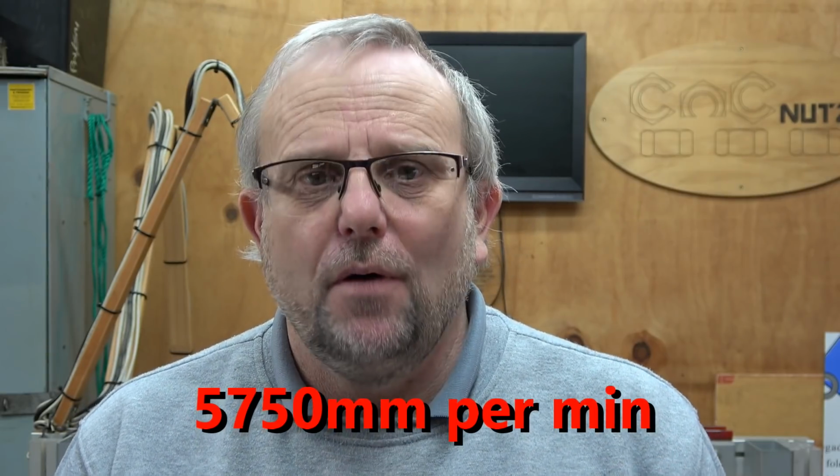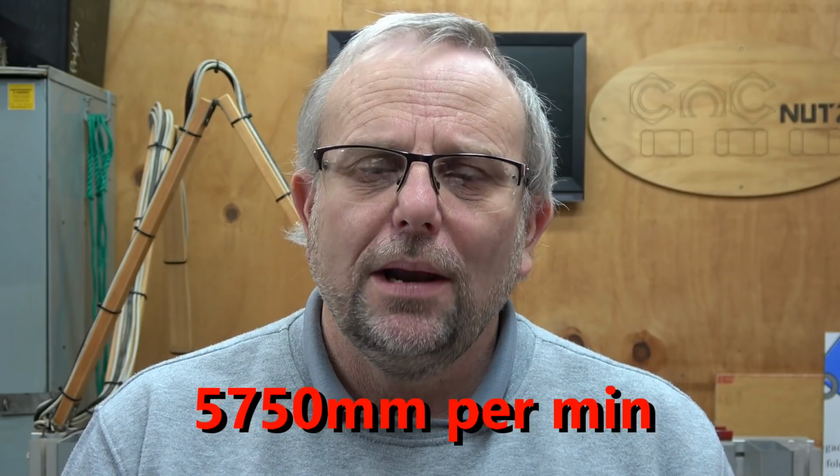What I did is I created a file with a feed rate of 2,300 millimeters per minute. That is 1/3 the speed that all of my other testing has been done. I then ran a feed rate override of 250%, bringing it up to around about 6,500 millimeters per minute, well below what all my other testing has been done at. It would not run smoothly around my oval.